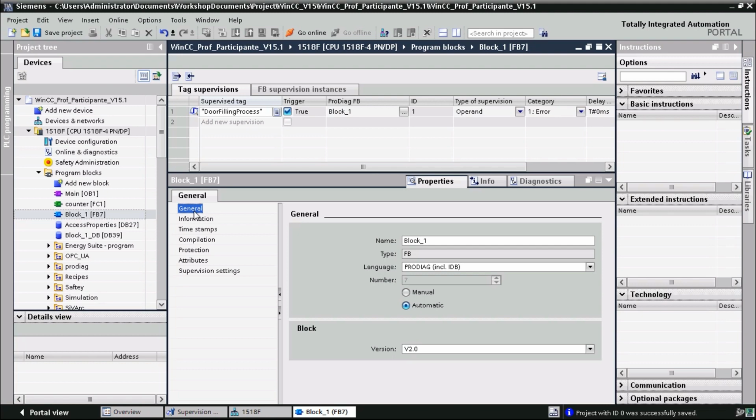Okay. And now I just hit the e-stop. Everything is powered off. I switch to my diagnose screen. By the way, this one here is the diagnose screen. And I see I do have a safety interlock and, oh, the interlock? Okay, interesting. Where is that?